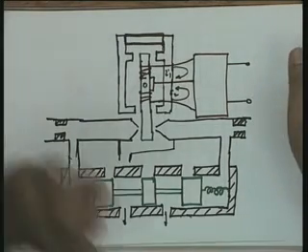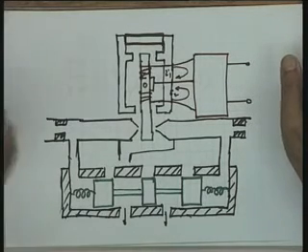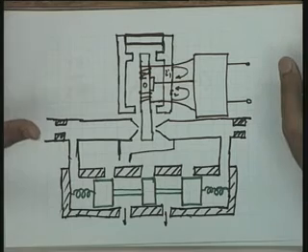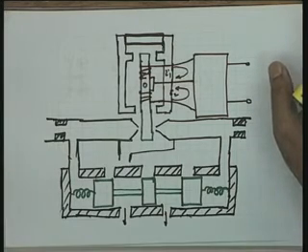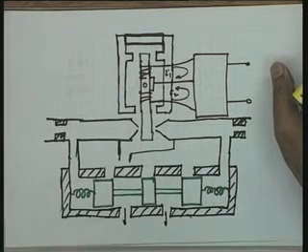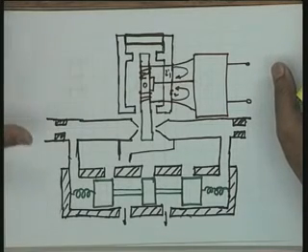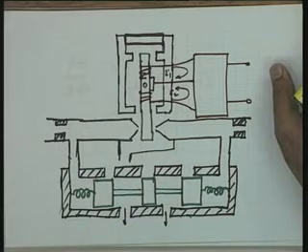Please see that. From the discussion we had so far, we could conclude that in many applications you will require hydraulic actuator and not electrical if the requirement of power is high. But if you go to the controller, recall what is controller. Amplifier only is not necessarily a controller. In a control action, you will require proportional action, derivative action, integral action, or even more complex function. Realizing these control functions through hydraulic equipment is difficult and is not even precise.